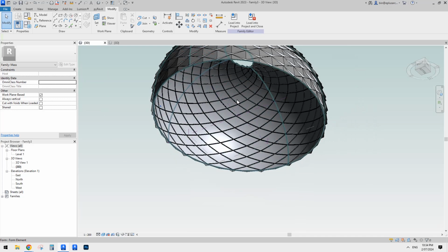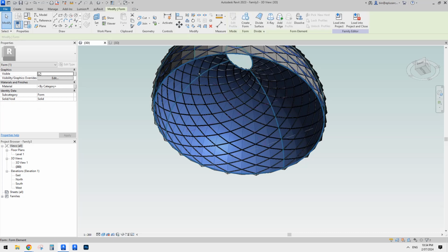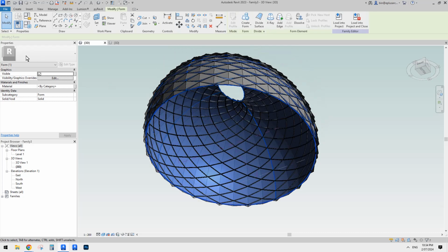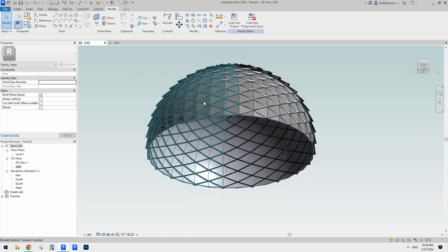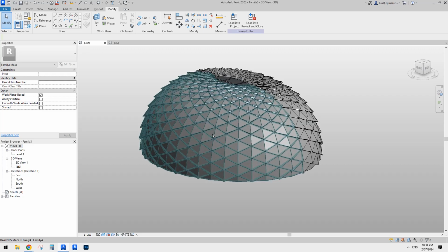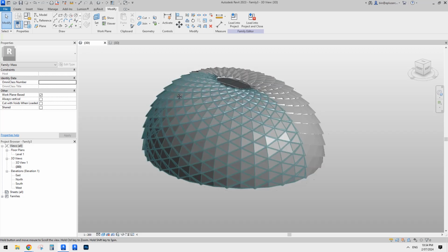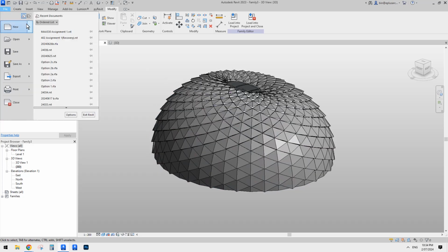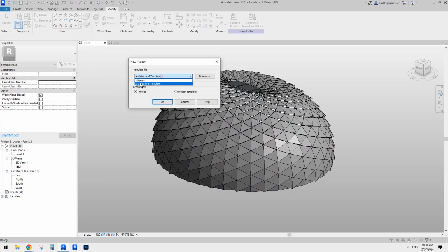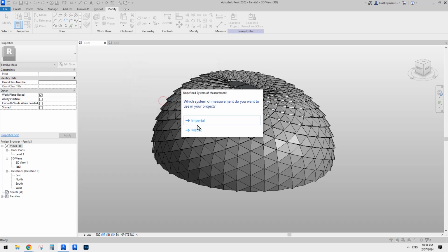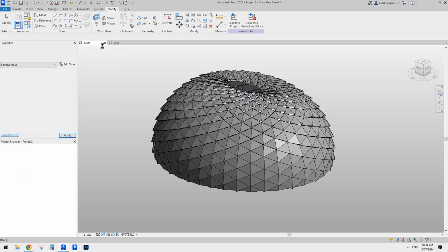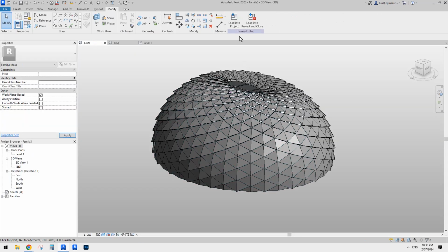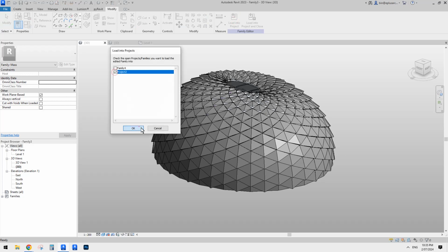What we can do is select this form. See here, visible, you can uncheck the visible. Once you uncheck the visible, you can make it invisible when you load it into, for example, a project. So I'll quickly show you. If I create a project, maybe without any template, and I'll just load this pineapple into the project.